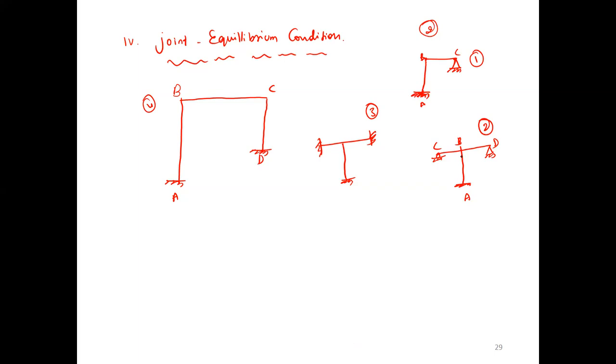Yes. For the second, how many equations? 3, sir. I think someone got it, yes, 3. What are those? At C, MCB equals 0. At D, MDB equals 0. At B, with members BC, BA, BD, MBC plus MBD plus MBA equals 0. Right. Here, 3. Here, 2. For this, 1. What is the 1? That is this one plus this one plus this one. Very good. Only 1.